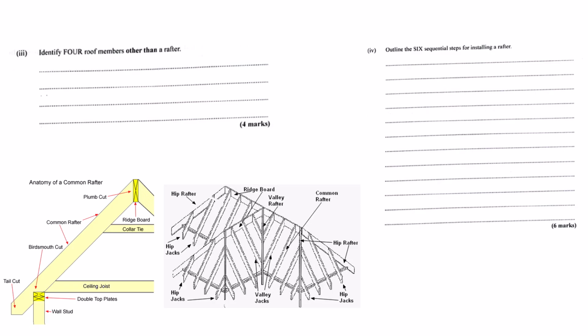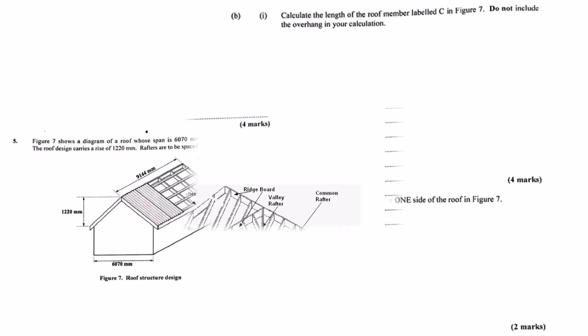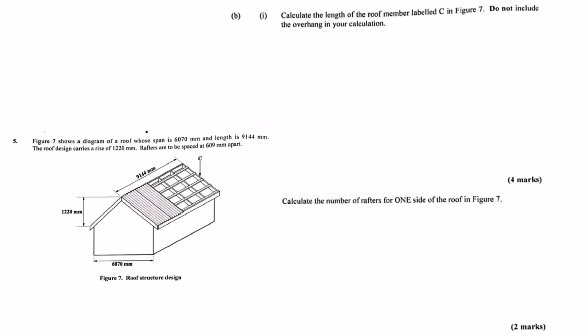And finally, step 6, secure it. Use nails or screws, properly specified ones, through the joints at both ends. At the ridge board and at the wall plate. At the ridge board and through that birdsmouth joint into the wall plate. Solid connections. It really is precision engineering, just with timber.